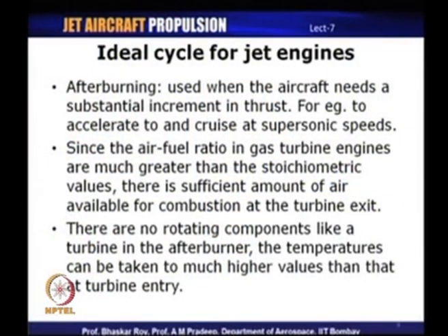And so, afterburning is used when an aircraft needs a substantial increment in thrust, for example, when it has to accelerate and cruise at supersonic speeds. And this is possible because the air to fuel ratio in gas turbine engines is much higher than the stoichiometric values, leaving a sufficient amount of air available for combustion. And the other aspect is that after the turbine, there are no more rotating components and there is no more temperature restriction as such, and therefore it is possible for us to have much higher temperatures than the turbine inlet